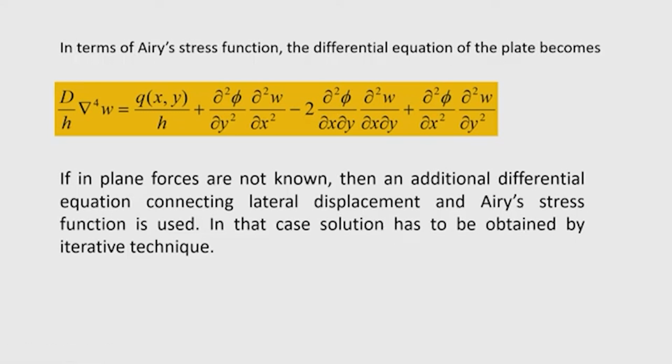Phi is the Airy's stress function, and phi is such that del²phi/del y² is sigma x, similarly del²phi/del x² is sigma y, and minus del²phi/del x del y is tau xy.